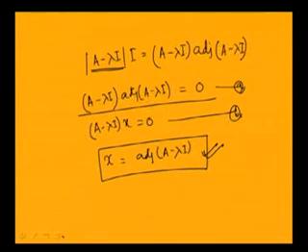We will take the example of a simple 2 degrees of freedom system. Let us take the 2-rotor system that we have studied before. Already you know that this 2-rotor system is a semi-definite system. In a semi-definite system, one of the natural frequencies is equal to 0 and you have a rigid body motion. Let us take this system for simplicity. Let I1 be the inertia of this rotor and I2 this inertia, and K the stiffness of this rod. Theta 1 and theta 2 are the generalized coordinates assigned to these two rotors. Now, you can find the normal modes.